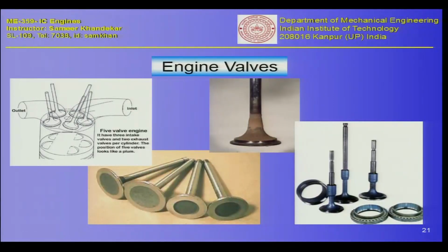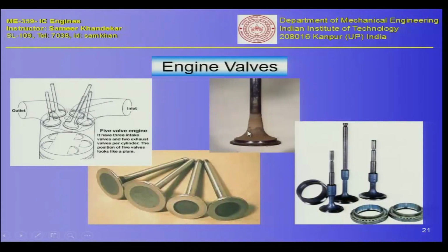Typically a petrol or a diesel is a mixture of about 150 to 200 different compounds, and there are also nitrogen based compounds. There are other impurities, there is silica waste in it, and silicon oxide. So all that burns, and usually you can see corrosion also taking place. The valve stem also shows corrosion, and very high wear and tear taking place on the exhaust valve.